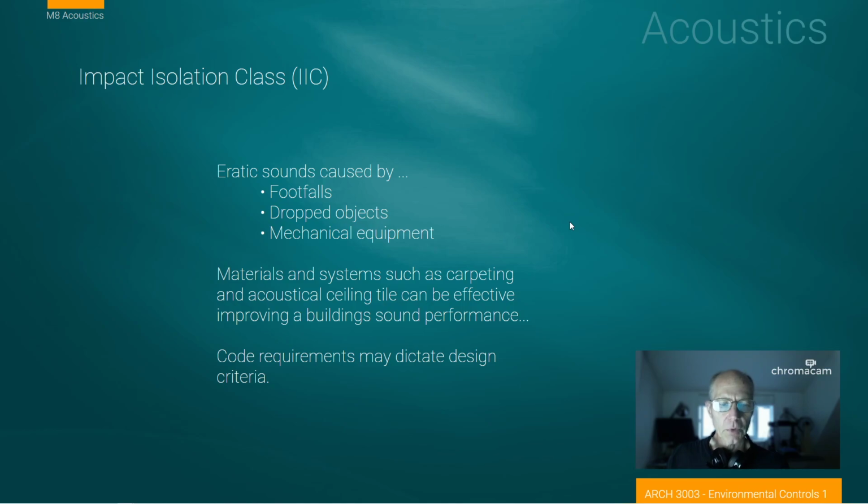There's another way sound transfers, and that's through this idea of impact. Imagine a wood floor. If you've ever been in an apartment where you have someone living above you and they're walking across the floor in hard shoes, high heels, and you can hear every motion that they're making. And the sound is being transferred through the physical impacts of the shoe on a hard surface. And so a lot of times we try to create surfaces that deaden that physical impact on the surface from being transferred to the next space.